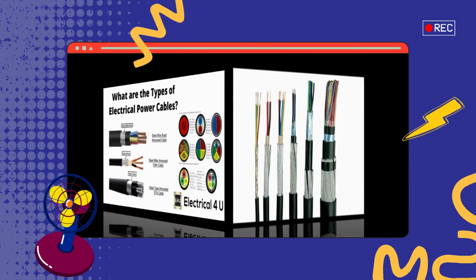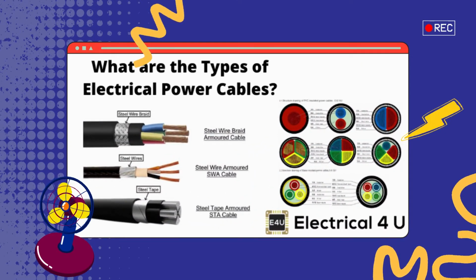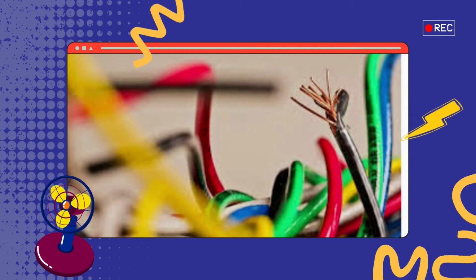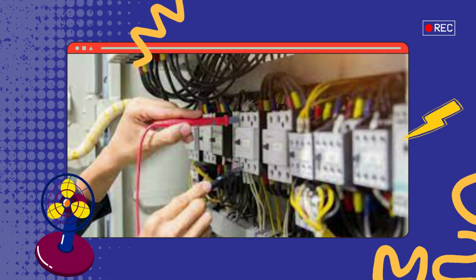Number 3, the current capacity of cable varies. Most people think that electrical wires retain consistent or stable current all the time, which is completely false. The truth is that the current capacity of wire varies with respect to the depth at which the cable has been laid, or with the ground or air temperature. Hence, it is very crucial to choose a power cable that is of good quality and has high endurance against any such factors.